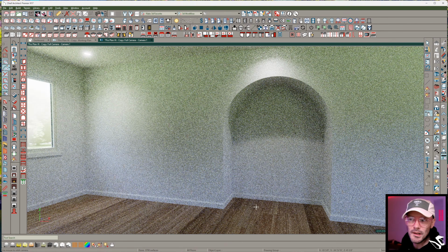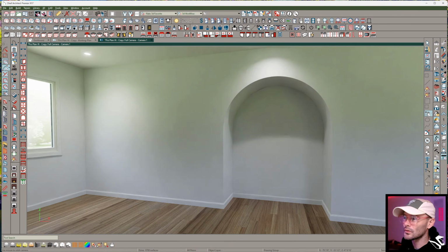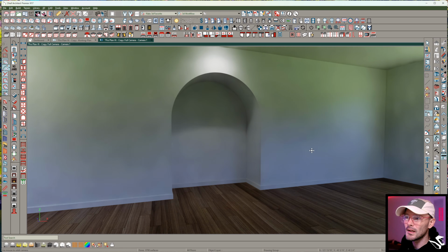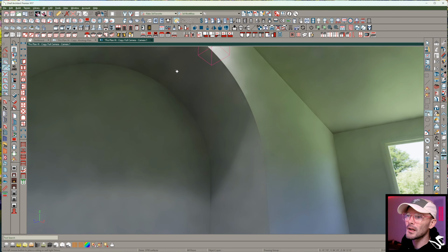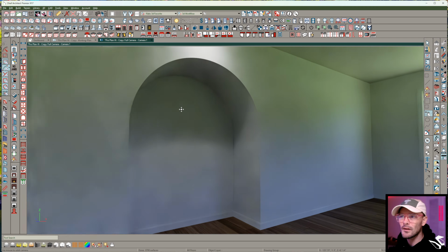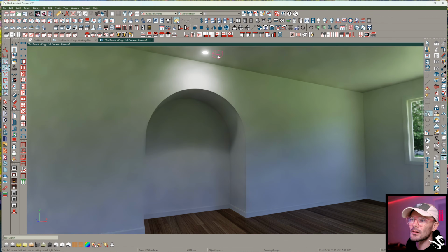The floor's finished into this room. All of our drywall transitions are there. That's all working correctly, and so we can see here, that did a pretty good job. Now, there's a new feature for dropping lights into ceilings. Because this is not a ceiling, that's one of the only pitfalls. You're going to have to do something in order to get a light up into the ceiling, which might mean that you change its offset from the ceiling, or maybe that you change it to a floor reference light instead.